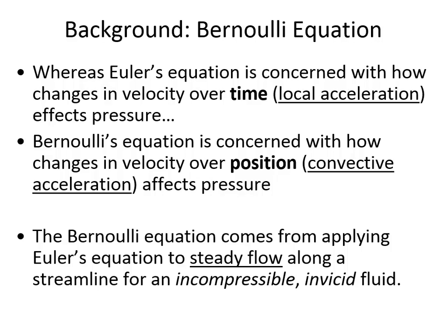There's no such thing as an incompressible fluid, right? So we're going to apply it in spite of the fact that it doesn't apply. But when you use it outside of the intended limitations, you're just going to see a little bit of inaccuracy. It won't be as accurate as it would otherwise be. So in the case of incompressibility, Bernoulli's equation is better for liquids than it is for gases.